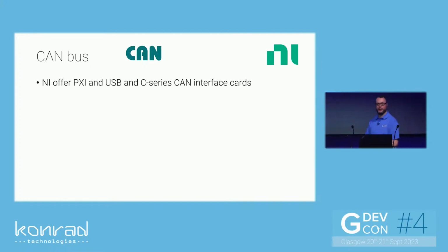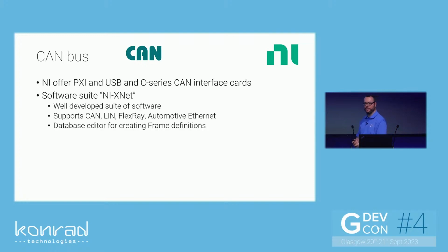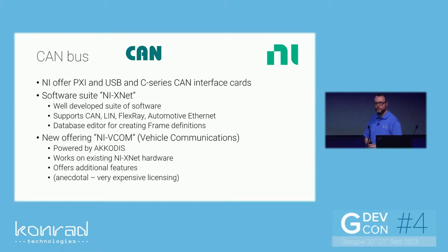So NI do offer PXI, USB, and C-Series CAN interface cards, which is good. And they released a software suite called XNet. It's a well-developed suite of software, good. It supports CAN, but also others like LIN and FlexRay, and automotive Ethernet, which is all good stuff. And the way that frames work on CAN is they're all predefined. So you need to have some definition of all of these, and my understanding is that's a database, a special type of database for CAN. So you need an editor, so one's built into XNet, all very good.